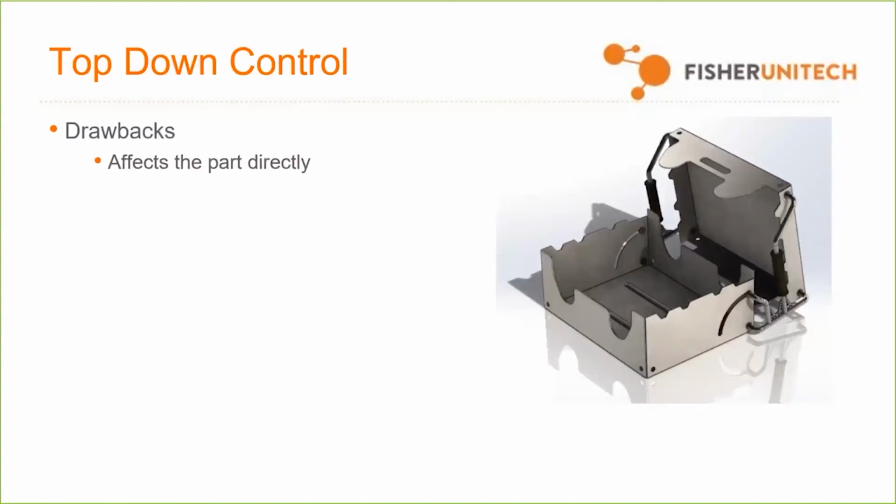So you can get around that. Just make sure that you have a copy that only applies to this particular thing that you're working on. You've got to pack and go every new configuration. So you change all the different dimensions and so forth, change up your assembly and your parts, and you want to pack and go that guy in order to have a different version of that assembly.